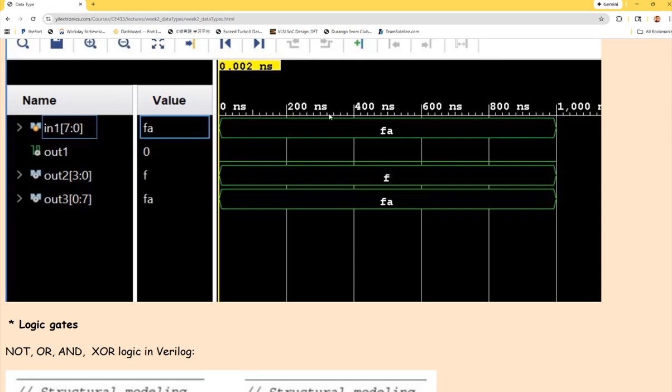it's not like an analog waveform display unit, right? It's not a monitor showing the analog voltages. So whenever it's not 0 or 1, it has to use something like this to represent it, right? It's a bundle of wires. You have to click it to expand it in order to see all the single digits, but there will be 8 wires that they put together. There's no way to display it because this is not 0 or 1. So it's FA. FA is 4 ones and then 1010, which is 10, right? So they just drew it this way, a box.